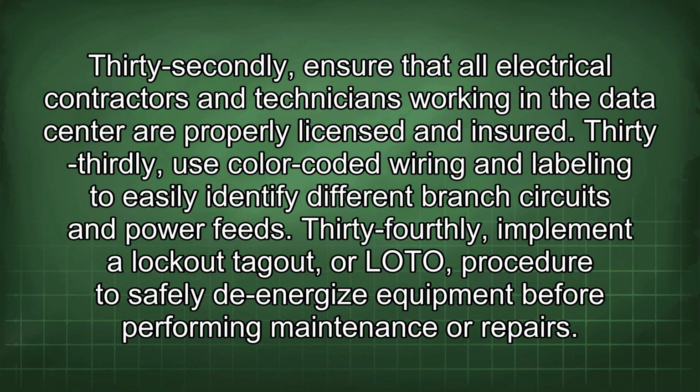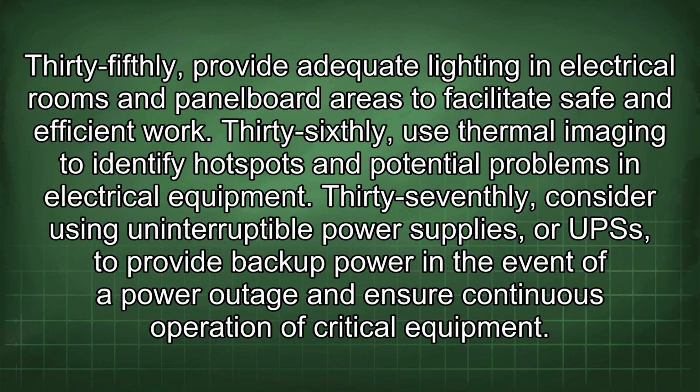34thly, implement a lockout-tagout, or LOTO, procedure to safely de-energize equipment before performing maintenance or repairs. 35thly, provide adequate lighting in electrical rooms and panel board areas to facilitate safe and efficient work. 36thly, use thermal imaging to identify hotspots and potential problems in electrical equipment.